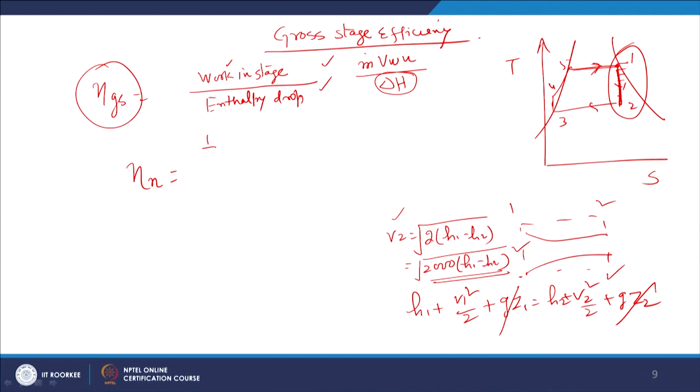Okay. So the nozzle efficiency, we can say, is the output energy going with the outgoing steam, that is half m V1 square, the steam which is leaving the nozzle, divided by the enthalpy change delta h, and multiplied by m, of course, because this is specific enthalpy. Now we know that blade efficiency is also something like that, VW U m divided by half m V1 square.